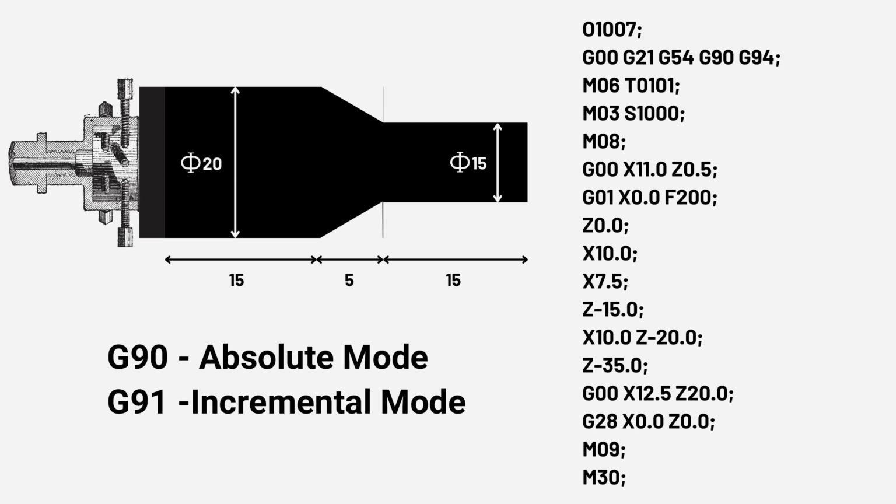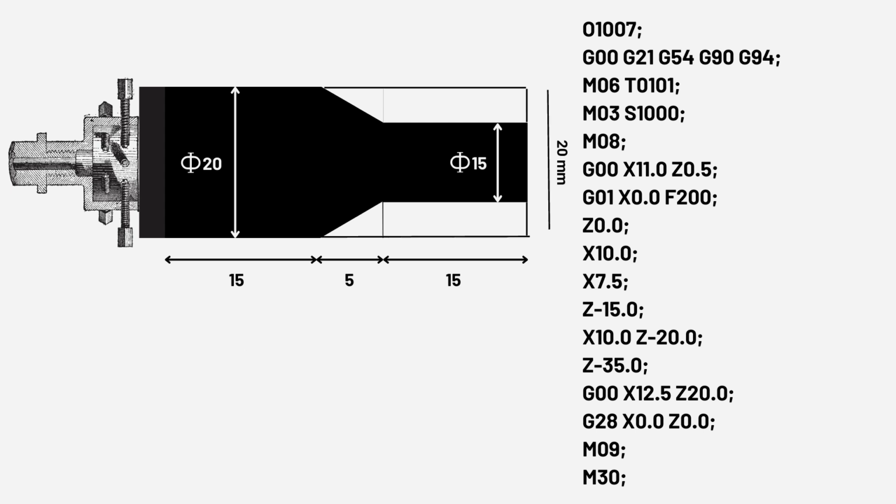We will discuss this later in the lecture, but first we need to define the size of the workpiece to undergo operation. In this case, we will need a circular bar of diameter 20 mm. This would be our workpiece. Now here we have to define a datum position from which the tool will start moving. So this point here is considered as datum and the tool will be moving from this point O to 1, to point number 3 and point number 4.